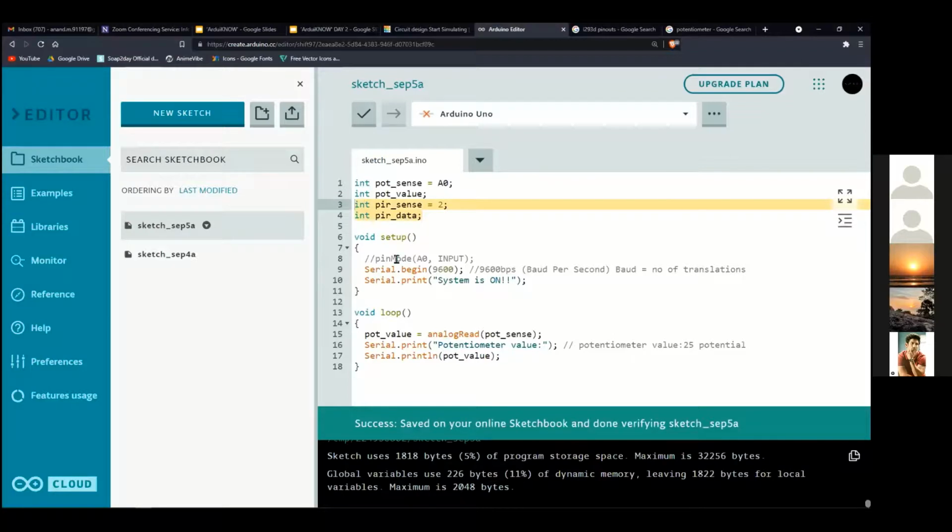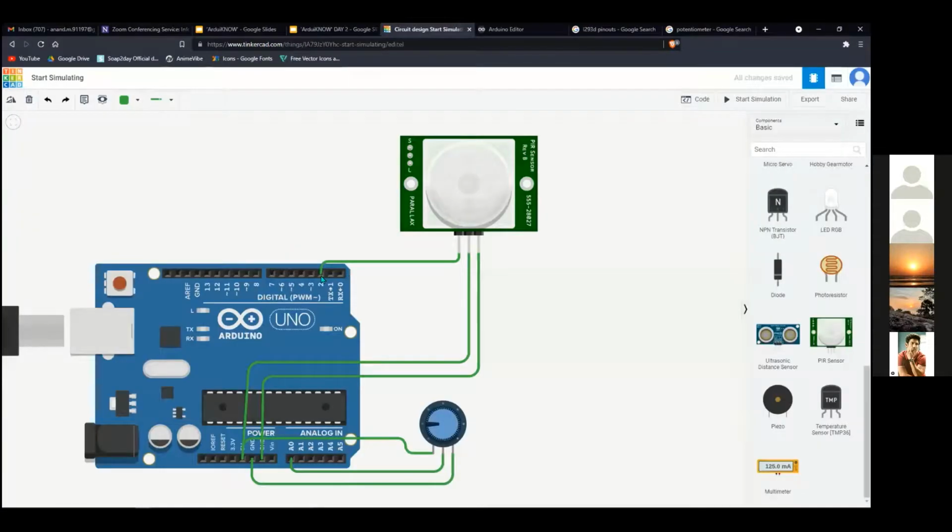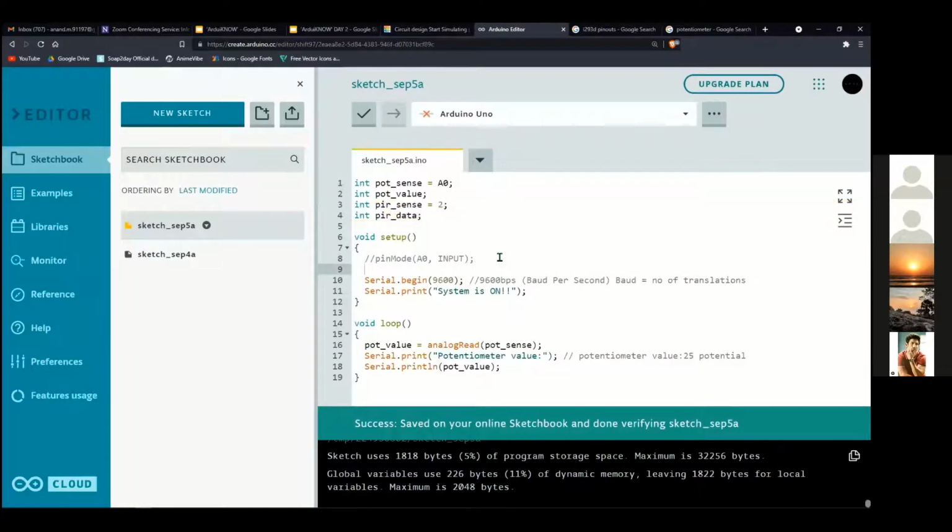So as we discussed earlier, since this is a digital input, we have to specify the pin number and the pin function in this void setup. Since it is not a dedicated one, it is a variable one, so you have to mention the pin format. For that, I will type pinMode under the brackets. I will name it as PIR.